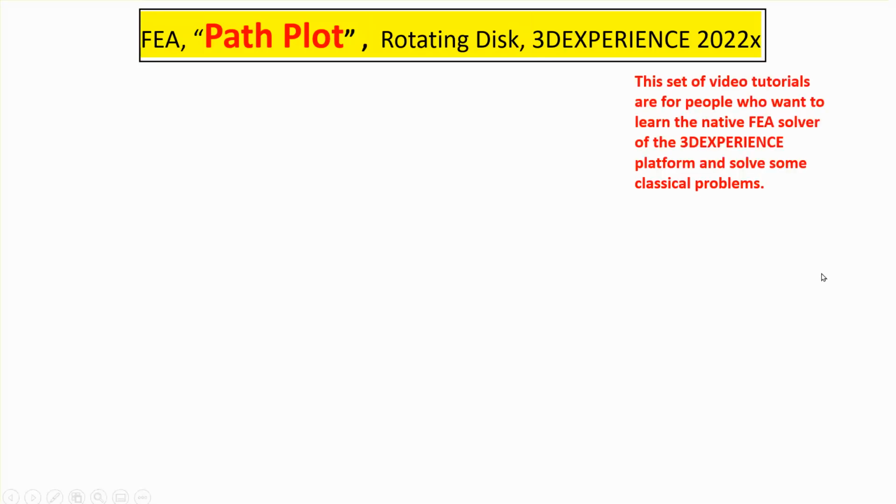The idea behind path plot is you specify a certain path in your model, and you will be asking CATIA, not CATIA, sorry, 3D Experience to plot certain entities that were calculated, such as von Mises stress, displacement, anything that can be obtained from the finite element results in 3D Experience, can be plotted on that path. Okay. So the specifics of the problem are here.